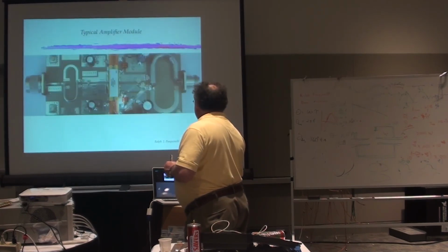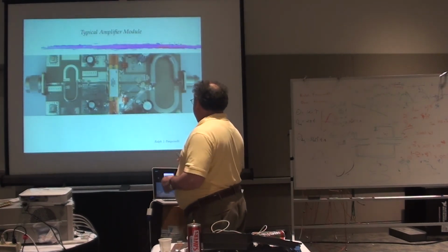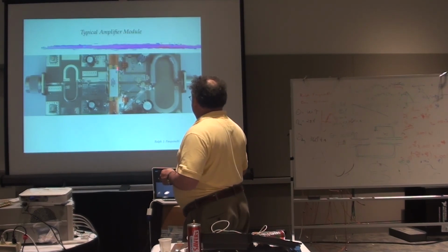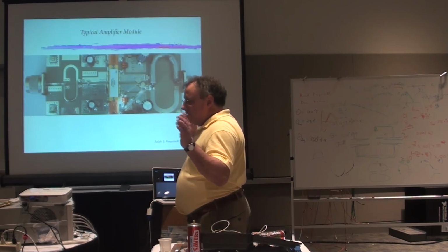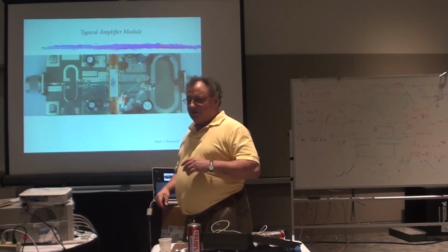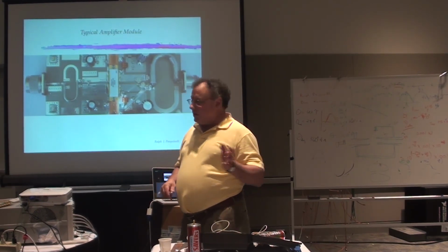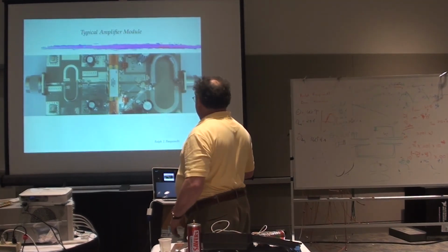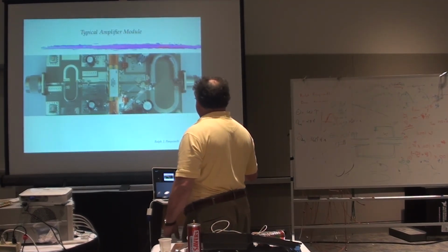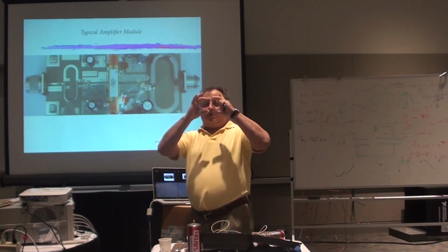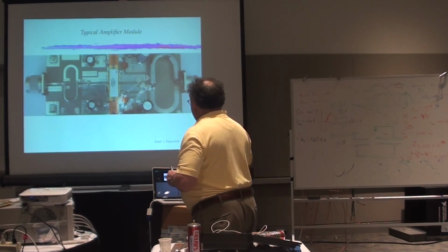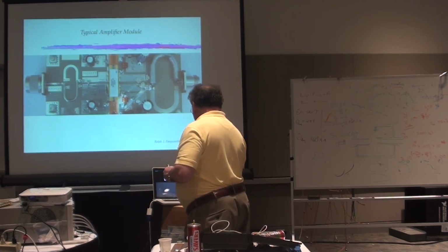Okay, here's a typical pallet of a solid-state amplifier. You've got, and these are typically, two MOSFETs in parallel. Could be done with gallium nitride. Silicon carbide is the newest thing for lower frequencies. And these little thingies here that you're seeing, those are actually hybrid transmission lines made using coax cables. And this whole thing is maybe 2 inches by 3 inches, something like that. And you've got hundreds of them built into a pallet.